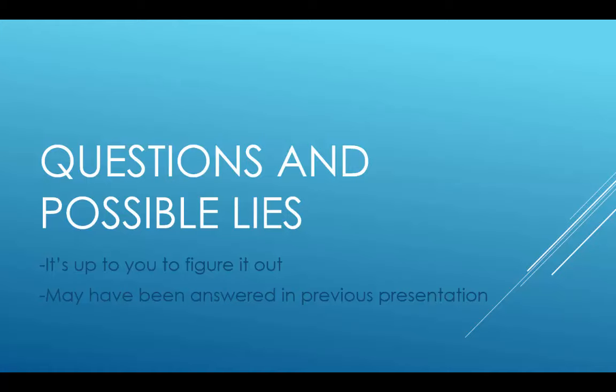Are you using configurations for the open and closed? Yes. Okay. One possible way around it is to use flexible subassemblies at the main assembly level, but that's a whole other presentation.